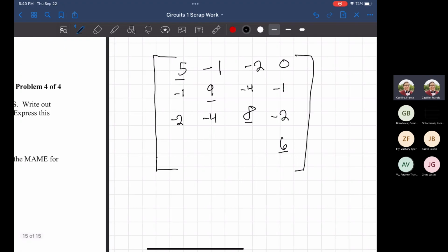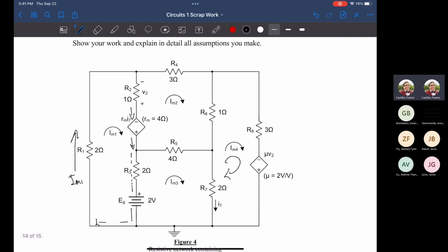Finally, we're on our last row where we put the sum in. Is there any shared component between mesh 1 and mesh 4? There isn't. That's going to be 0. Between mesh 2 and mesh 4, we already know from filling in our previous rows that R6 is being shared. When you're working on the later rows, it'll become a habit to look at your previous numbers and realize that between mesh 4 and the others, there's a shared component of R7 and R6.